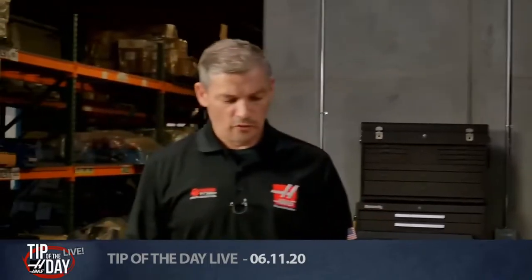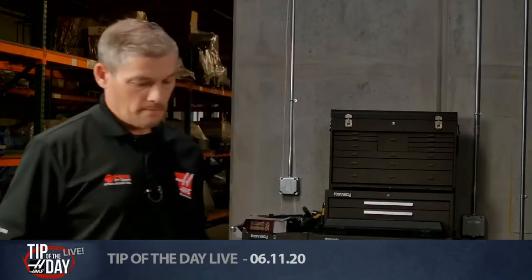Good one. Okay, this is from several weeks ago. TCF Precision Machining asks, is there a way to lock out the probe length offset in a VMC next-gen control? I know you can lock out all the offsets, but I hate accidentally modifying the probe length offset. Yeah. So I was job shop for a lot of years, and so I'm changing the tools out of my machine every day. I mean, everything. The whole carousel dumped and new tools coming in. And the way that I start my setups, the first thing I do is I go to the tool offset page, I press origin, and I clear out all my tool offsets.